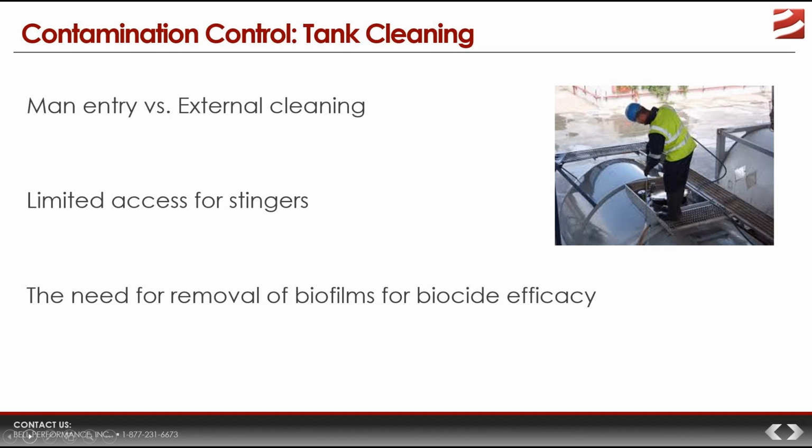So what most companies default to is external tank cleaning, where they'll have a fuel polisher or a tank cleaner come out and use stingers and suctions to suction out as much of the water as possible and as much of the biofilm as possible. Unfortunately, we know that because of the way biofilm is distributed, you're probably not going to get it all, but you try to get as much of it out as possible.